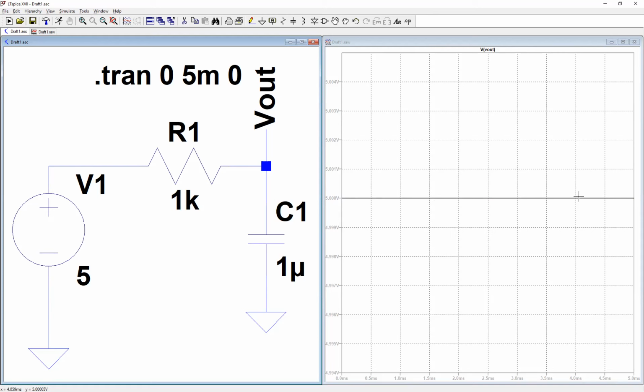And if you did not know from the theory that the capacitance charges exponentially, you would have guessed that this plot is correct. And for this reason, again, as I say in class, you should never trust the simulator without having an estimation or a guess about what will happen in the circuit, because otherwise you practically will believe blindly the simulator, which, if not set correctly, will give you the wrong answer.